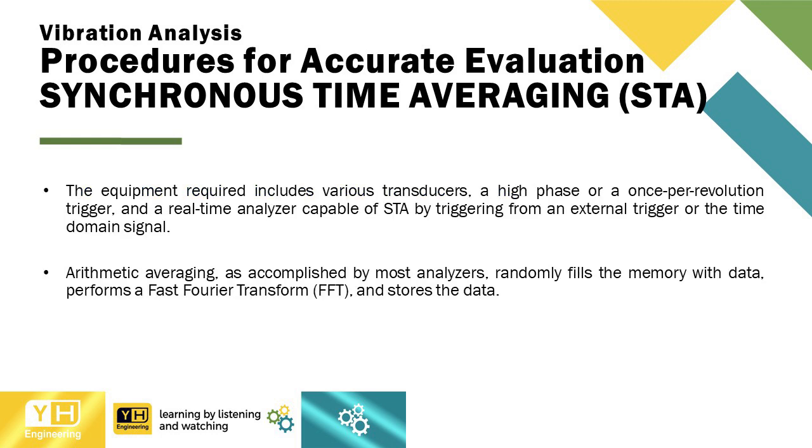The equipment required includes various transducers, a high phase or a once per revolution trigger, and a real-time analyzer capable of synchronous time averaging, or STA, by triggering from an external trigger or the time domain signal.